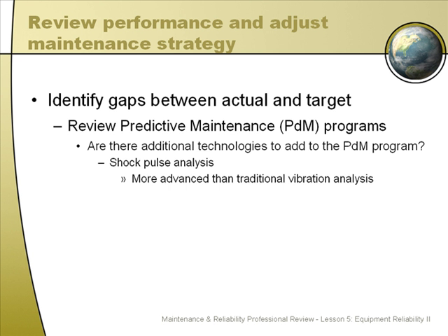Another more advanced tool using similar techniques to vibration analysis in a different way is shock pulse analysis. It's more advanced, and it also has some applications that will allow you to specify what kind of defects are occurring, for instance, inside a bearing, right down to the last detail. I would recommend that you take a look into shock pulse analysis if you have a use for knowing very specific information about why a failure is occurring.